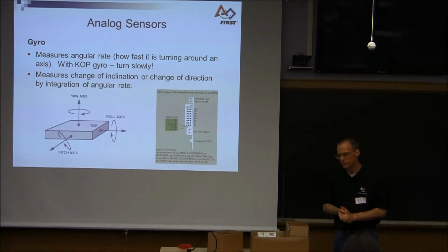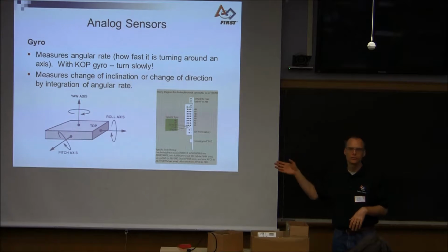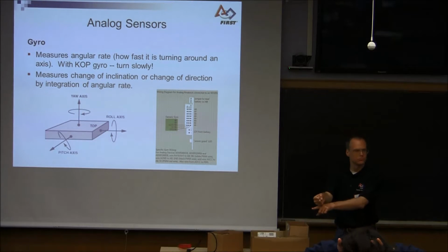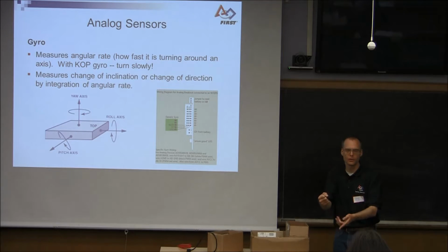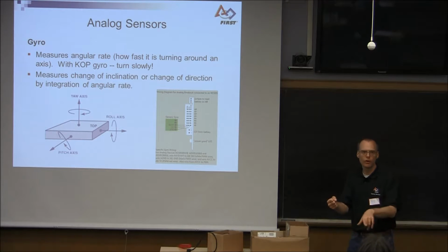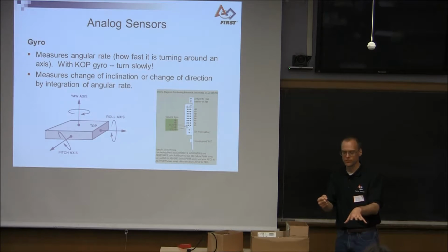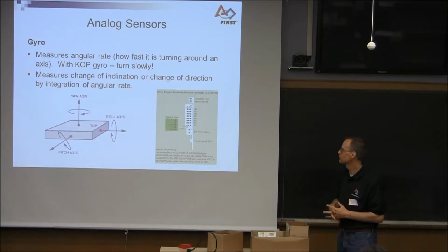Getting back to the Mecanum, what the software is doing is it's taking the data from the gyro and comparing it to the angle that you're moving the joystick constantly, like maybe 10, 12 times a second. And then dynamically adjusting the power to all four wheels so that the robot is moving at the same angle that you're moving the joystick. If you do not have the gyro on there, you're going to find it's really hard to steer that robot, and it's going to want to do all kinds of fun things.